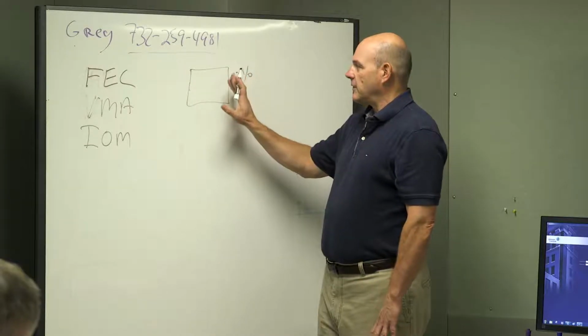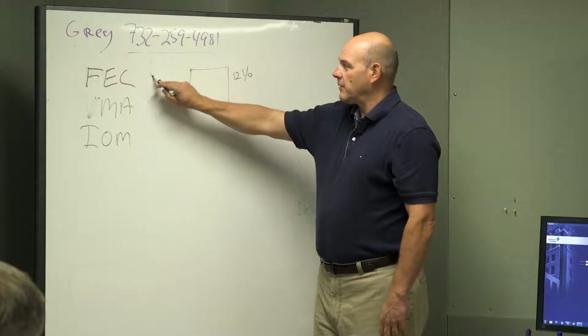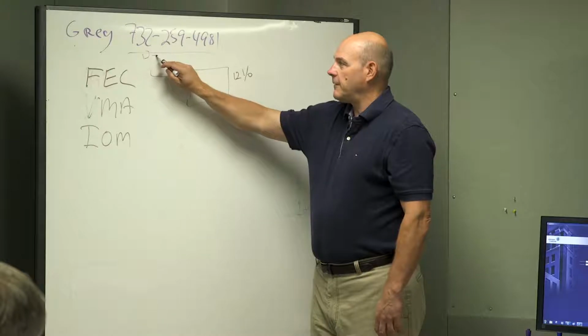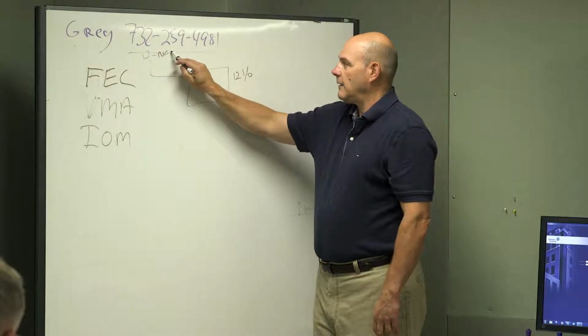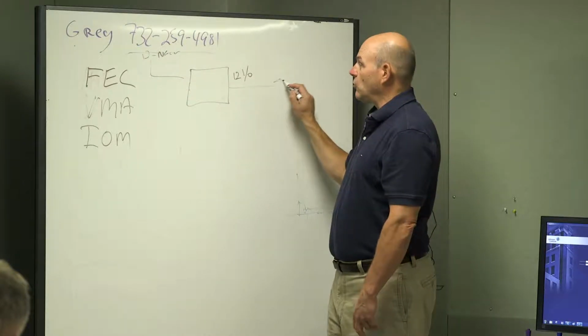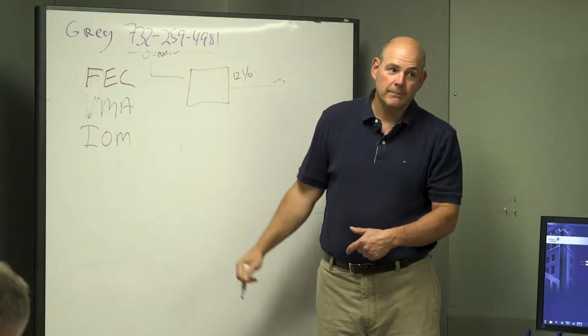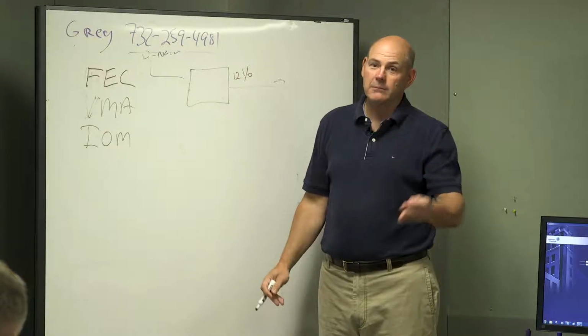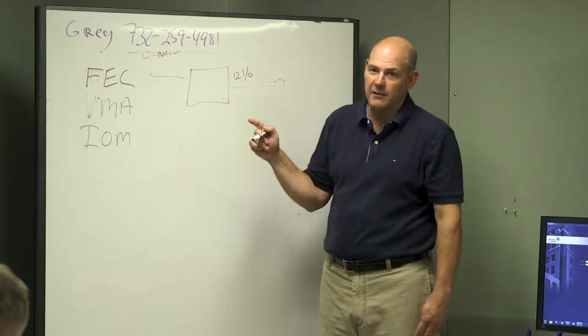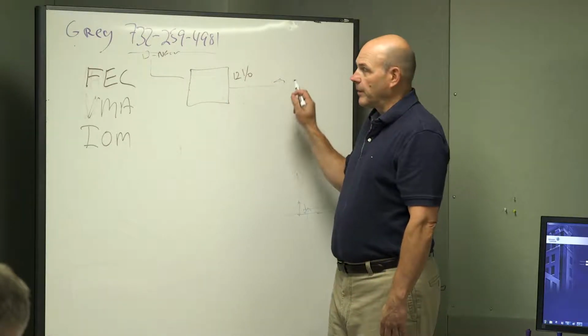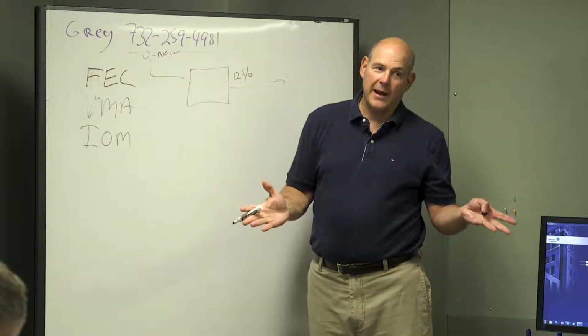And there are various types, and that's going to be on the loop from your NAE, NCE, and FAC. And like I said, you could theoretically put 99 on one loop, but again, point count matters. If you put a VFD on there, it's on the same loop, you're sucking up a lot of data.